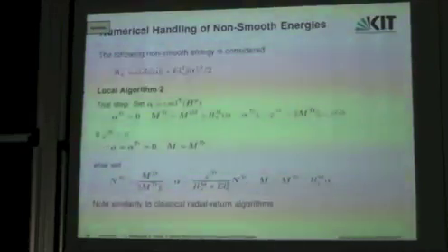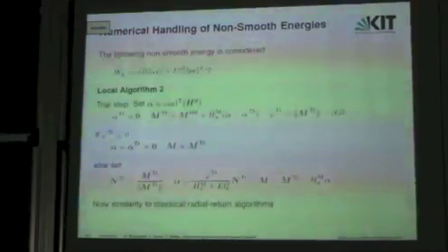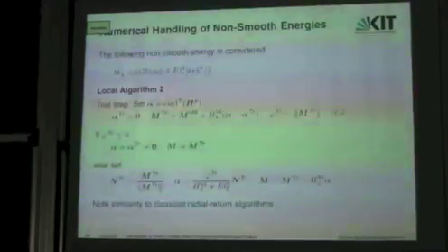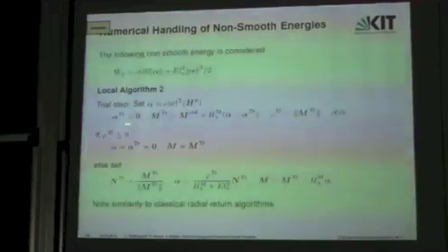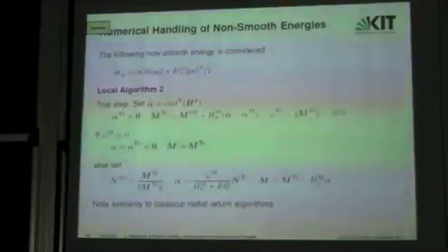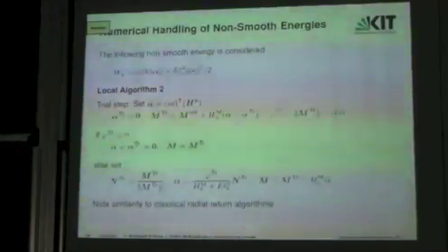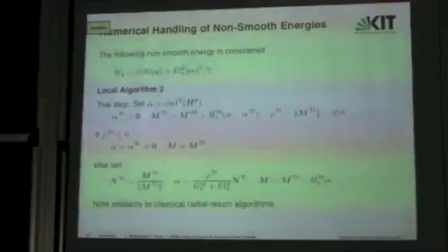I talked about this yield criterion, or generalized yield criterion function phi, and this yields also a local algorithm which is very close to classical plasticity algorithms. Now look at the computation of your generalized stresses. We start with the trial step, compute trial generalized stresses and a trial value for your generalized yield criterion. If the yield criterion is not fulfilled, then the trial step was right. Okay, then you have your stresses here.